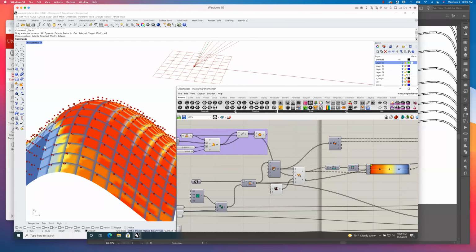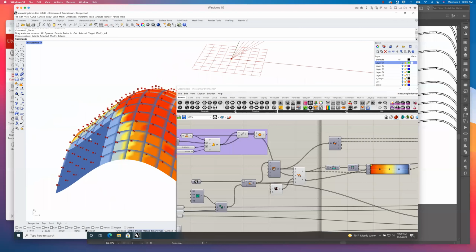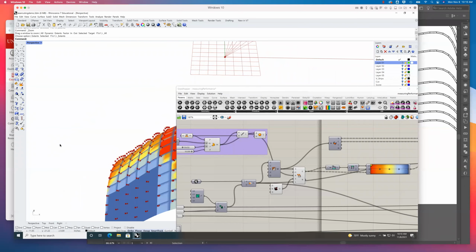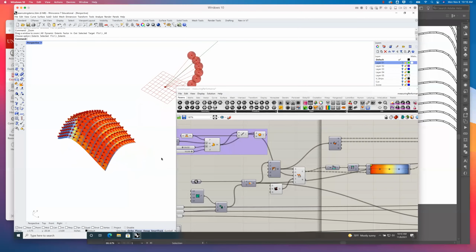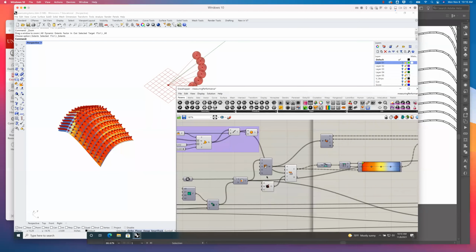And then in places over here where you see blue, right? These are areas where each of those points are populated with the rays, but the rays are occluded by the rest of the geometry, right? So the surface actually self-shades itself along the northwest side here, since we're measuring for morning sun angles for a particular date, right? Okay. So it takes all of that information and calculates the amount of solar radiation hitting each of these